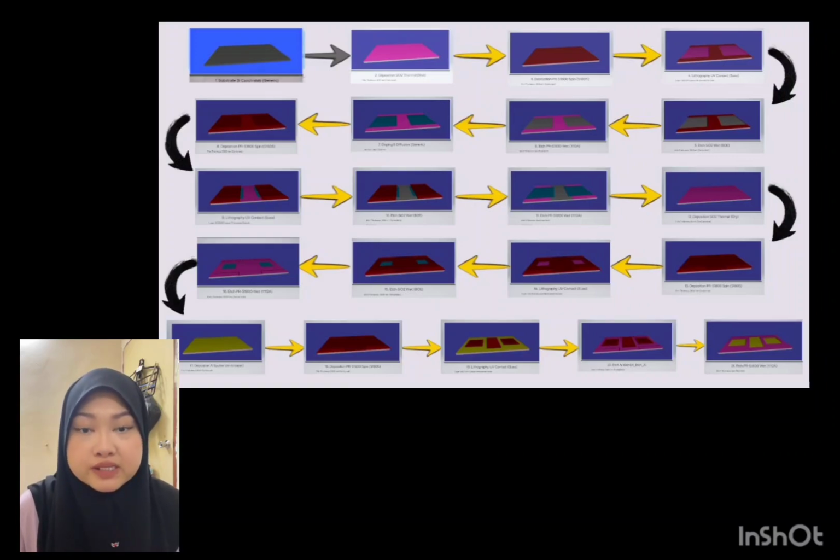The steps of coating, exposure, etching and cleaning are repeated multiple times using different masks to gradually build the device structure. Later, a thin oxide layer is grown using dry oxidation for better control and precision. Finally, aluminium is deposited using the sputtering process to form metal interconnections. Another photolithography step defines the metal pattern, and unwanted aluminium is removed through etching. At the end of the process, the wafer contains a complete device structure ready for testing.